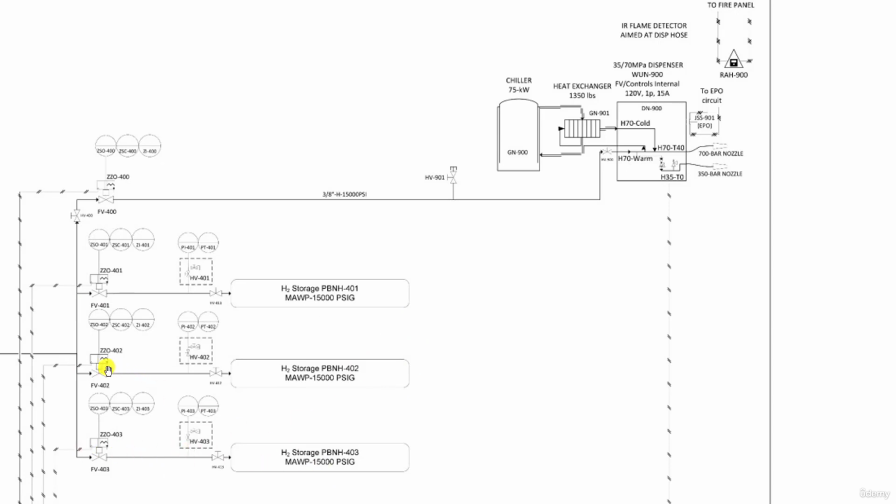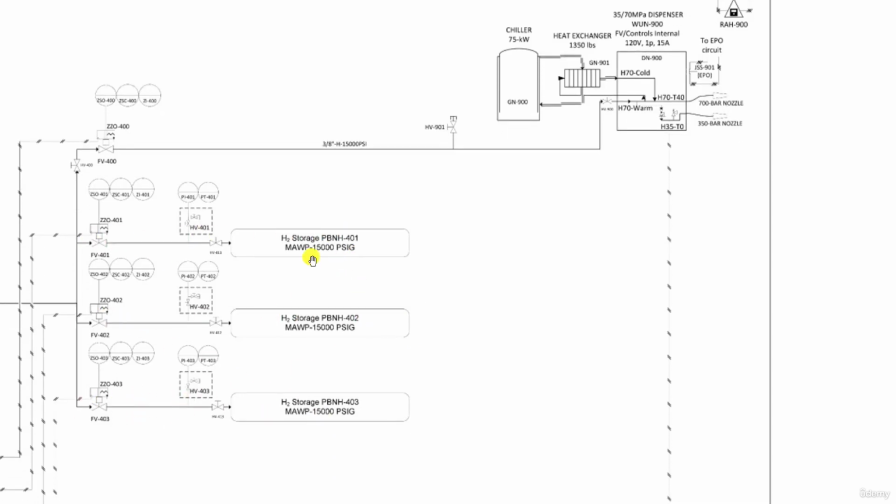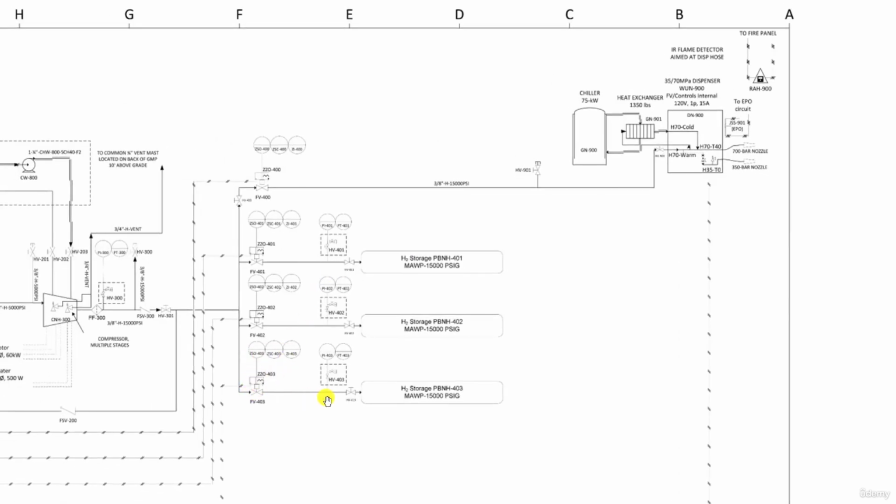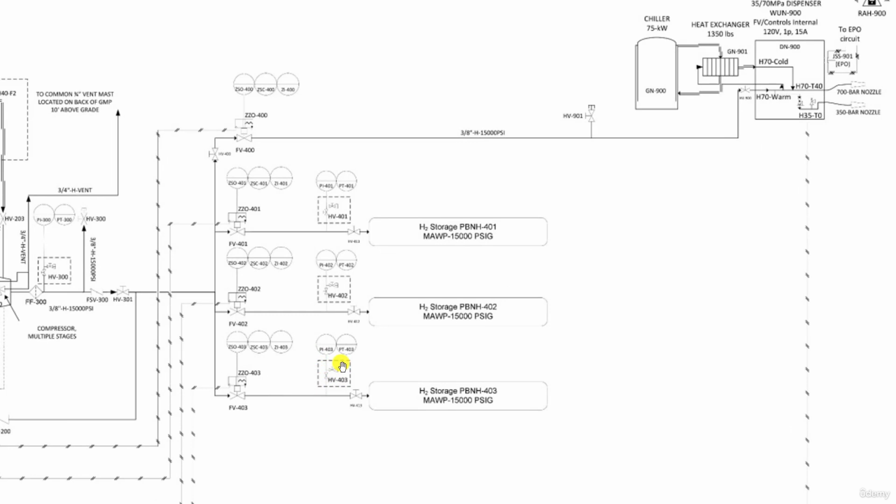Now, these are identical arrangements. In each case, first you have an air-actuated valve with limit switches, then a process connection to pressure instruments, then a hand valve, and finally the storage tank. In this P&ID, you don't have details related to the storage capacity of the tanks. We don't know their design pressure, and we don't know their design temperature. Perhaps there is another P&ID depicting these storage tanks with more details. Also note here the same isolation system on the pressure instruments to allow safe maintenance operation.